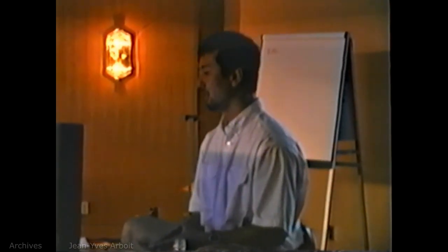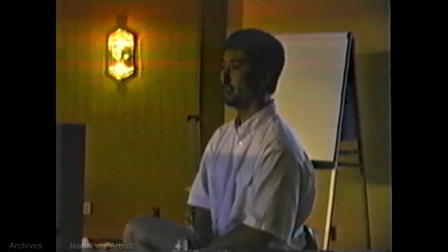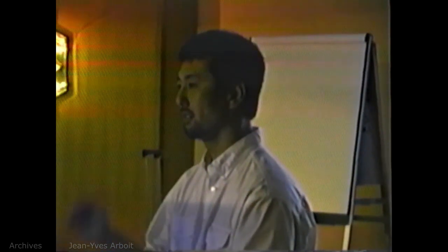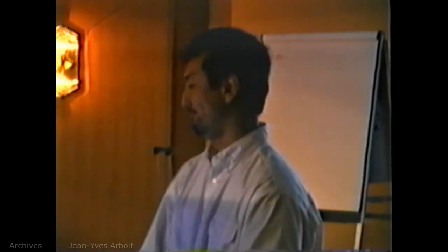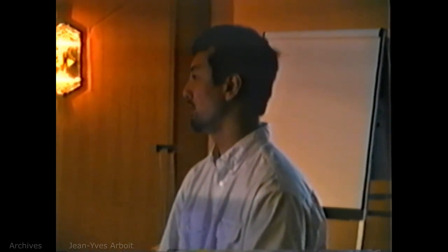So just a heads up, that is a difference between IRIX and NT: they will spell out that they have X amount of video RAM and X amount of texture RAM. You'll need texture RAM for the interactive display, so you're getting your textures on there, or for the multi-lister display, so things like that will speed up.